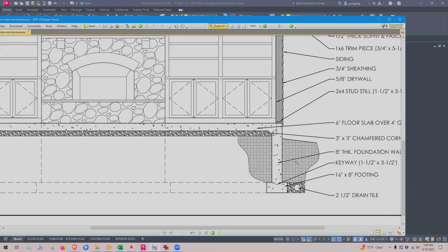And what we don't want is for our water to come down and sit at the footing down here, if we can. We want to get it away from the house. So what a drain tile does is the water that is near the house will come down into this area that has some stone around this tile. Water can move through stone a lot easier and quicker than it can through the soil, and it comes down and then goes into this drain tile.